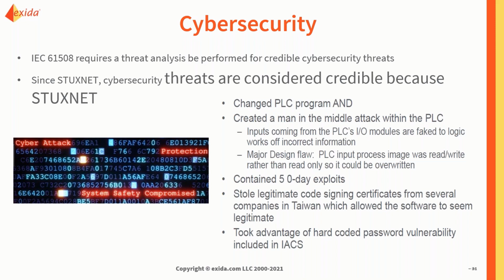The main design flaw in this part is that the PLC input process image was read and write rather than read only, so it could be overwritten from the client side instead of only being controlled by the PLC. What happened was that it contained 5 different zero-day exploits, and they stole the legit code, did something with it, and then reintroduced it back into the system.